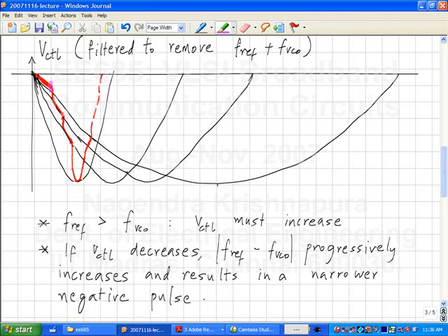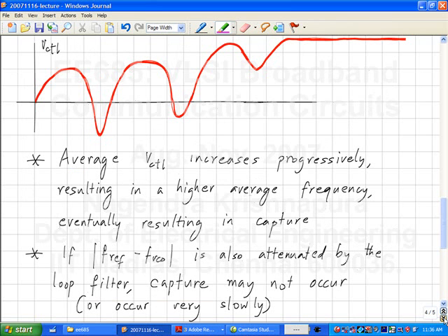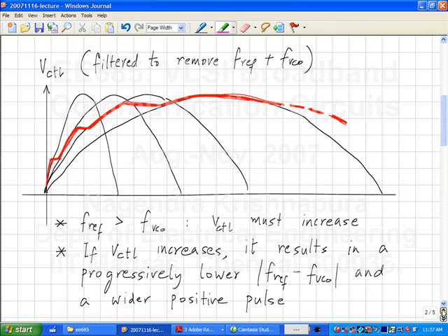So, I will say that it switches from this curve to this curve. Okay. And next it switches to this and switches to this. So, it is only when the control voltage becomes positive again that it will start increasing. Okay. So, essentially if you look at a PLL under capture, so let us say it starts off like this. Even if it starts off positive, it may not capture immediately, because it will follow this, but it may eventually fall off because the time is not sufficient for the frequency of the VCO to have changed to the right value.